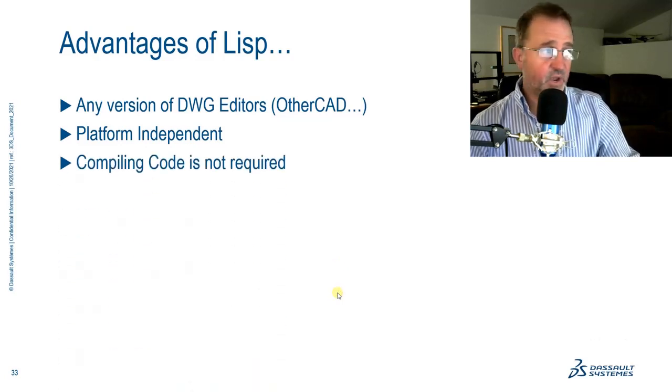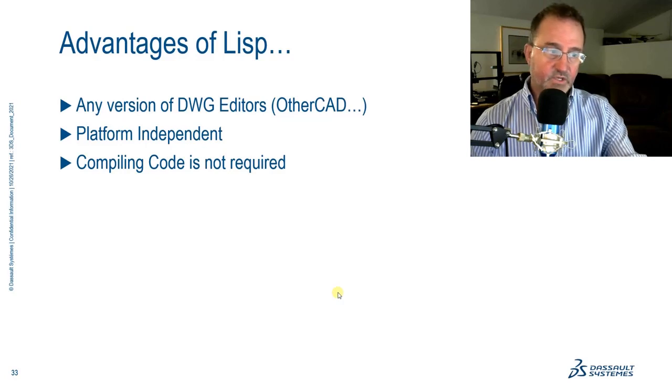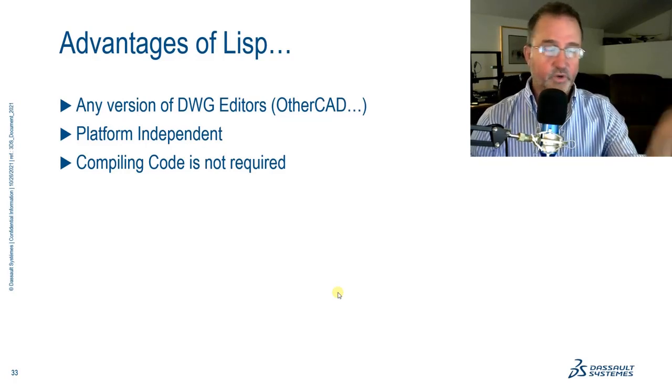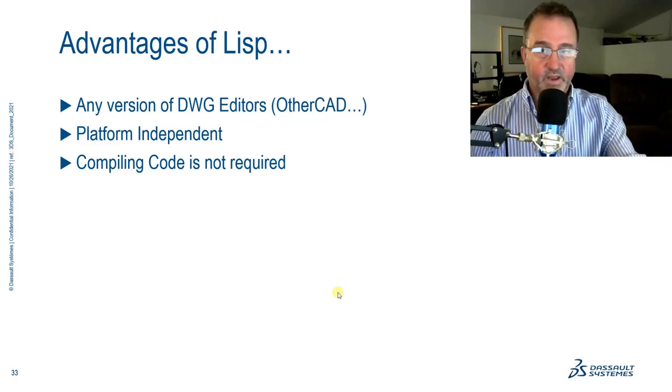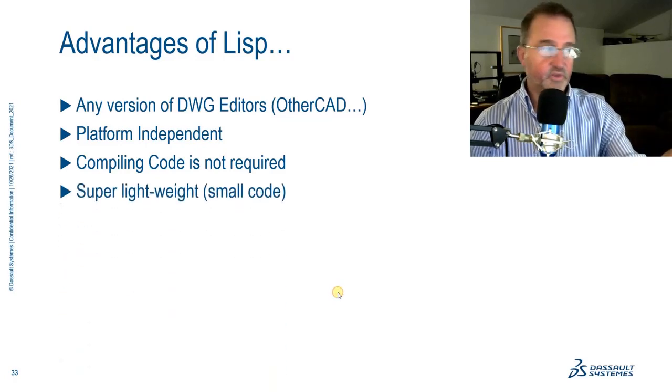Also, you do not have to compile the code. If you looked at that startup Lisp routine that I created, it wasn't compiled. It was just text that I put into a notepad file, and it's called an LSP file. I can use Notepad to edit that, and you load it and it runs automatically. You do not have to compile the code in Lisp.